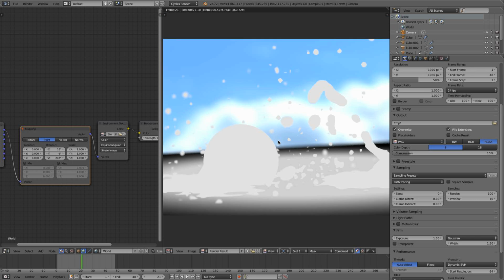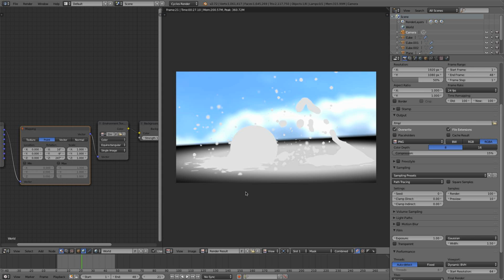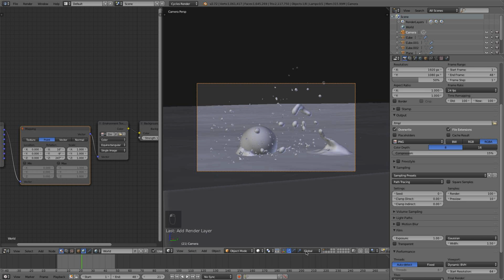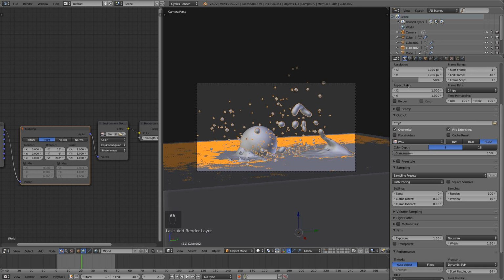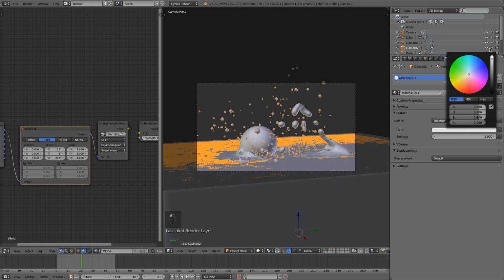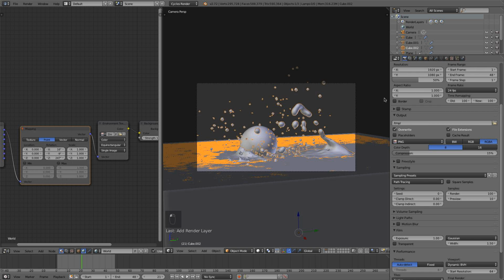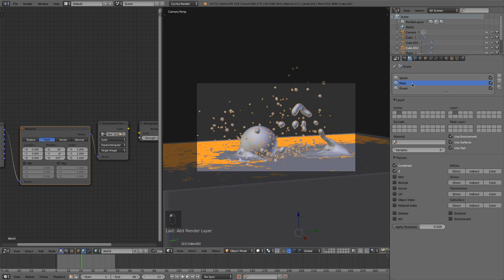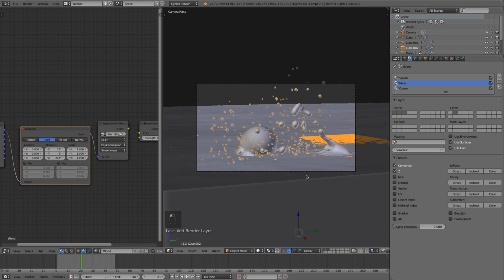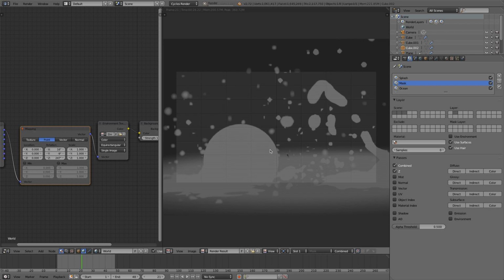Alright, now this finished, and if I scrub through my different layers over here, I left the background rendering in my mask, so I need to quick fix that. And it also looks like I didn't put my emission color at 100% white, so I need to do that as well. Layer 2. The material and the emission needs to be 100% white. Very cool. And on the render layers, layer 2, we do not want the environment. So uncheck use environment. Awesome. Now we should be good. Save, select all three of our layers, and let's do a render.